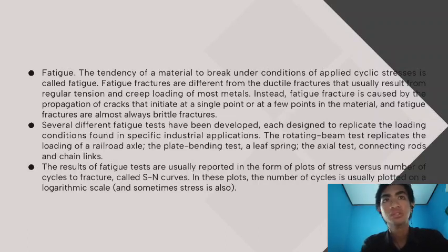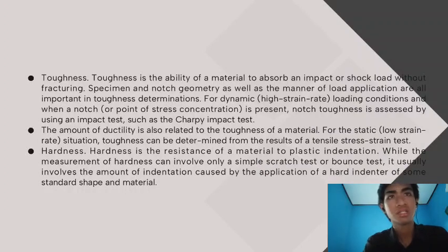Okay, we next to toughness. Toughness is the ability of a material to absorb an impact or shock load without fracturing. Specimen and notch geometry as well as the manner of load application are all important in toughness determination. For dynamic loading conditions and when a notch is present, notch toughness is assessed by using an impact test, such as a Charpy impact test.